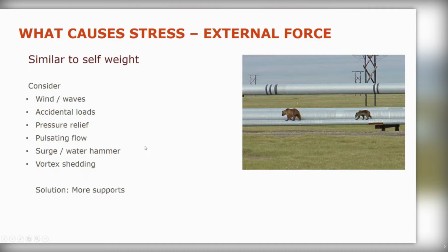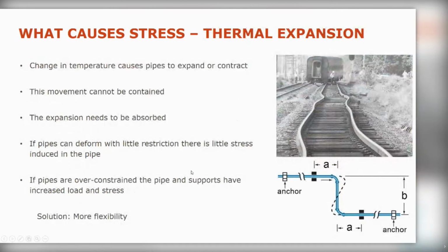But basically, external forces. Again, you can basically treat it as simple beam theory. Apply the load between the supports, either as a uniformly distributed load or point load, or a combination of the two, and you can work it out. And again, if in doubt, you can always add more supports. Your pipe will be restricted in movement, and therefore, you'll solve the problem. Probably, again, if this is all you worry about, you're not at high risk that you really need to do formal pipe stress analysis, because nothing complicated is going on.